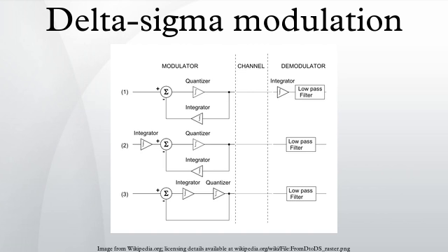In general, delta-sigma has some advantages versus delta modulation. The whole structure is simpler, only one integrator is needed. The demodulator can be a simple linear filter to reconstruct the signal. The quantizer can have full-scale outputs. The quantized value is the integral of the difference signal, which makes it less sensitive to the rate of change of the signal. Principle: the principle of the delta-sigma architecture is explained at length in Section 2.